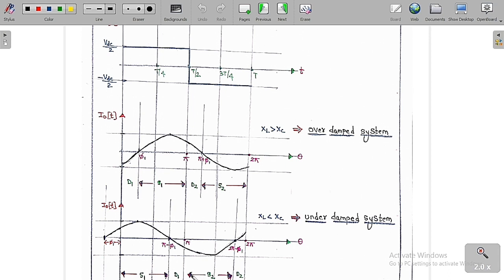See, when D1 is on, by default a negative voltage is going to be applied across the switch S1. So simply we can say that switch S1 is going to get turned off. Similarly here, when D2 is on, at that instant a negative voltage is going to be applied across switch S2. So the switch S2 is going to get turned off. So no need of forced commutation to turn off the thyristors. Whereas here, yes, you need to forcefully turn off the thyristors. Here, by default, the parallel diode is going to conduct. Whenever it conducts, it produces a negative voltage across the switch. Therefore, it is going to get turned off.